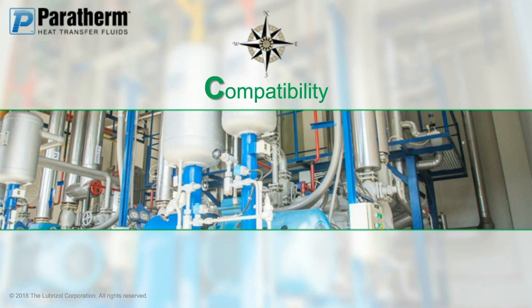When you're topping off a fluid and you have an aromatic type base fluid, or you have a fluid that's in there of a certain kind of classification or chemistry, and you decide to switch suppliers and either go for a fluid that has A, more capability to give you an extended range, or B, something that might be more cost effective for you, odds are you're going to run into problems with compatibility of the fluid that you're putting in or the fluid that used to be there. So a top-off issue is very important to consider, because you're putting a smaller percentage into a bulk of a fluid.